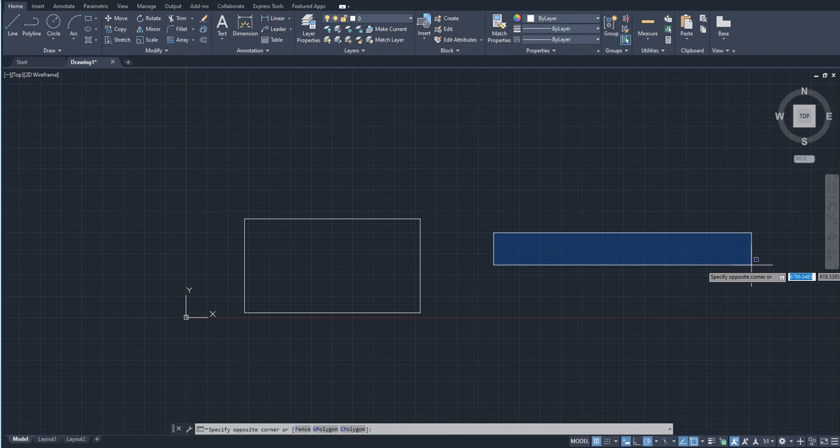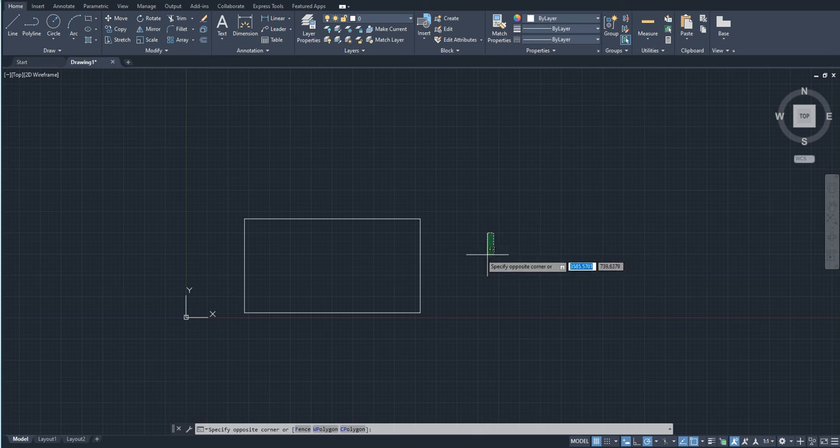box has appeared, and if I move it to the left hand side, a dotted green box has appeared. These two different boxes denote different types of selection. I'll just show you what they do. Now if I select this box using the blue solid selection, for that I just have to click towards the left hand side of the object and drag it towards the right.